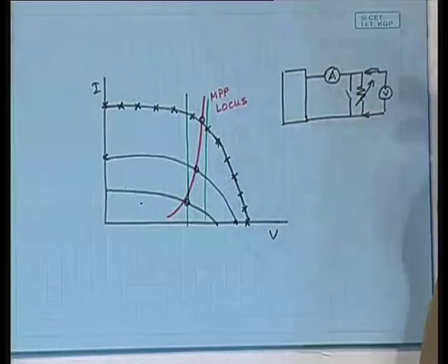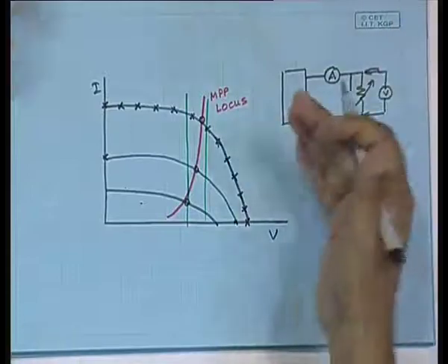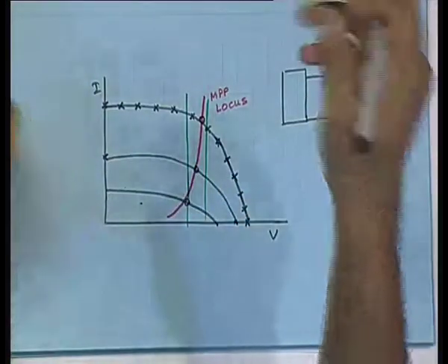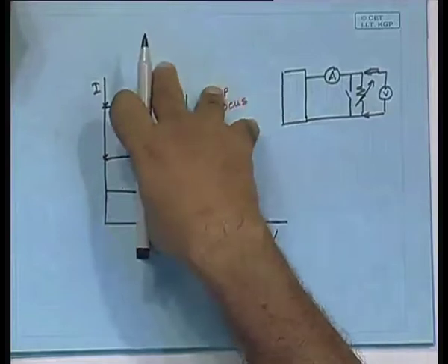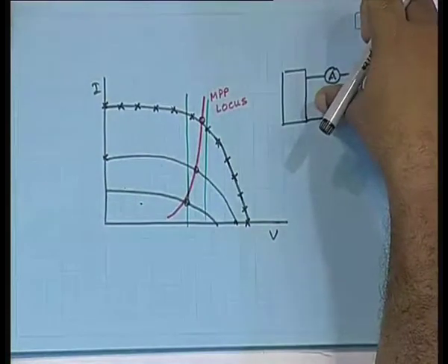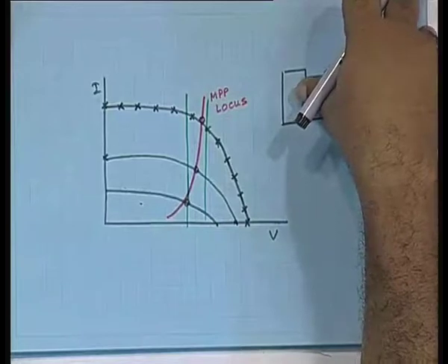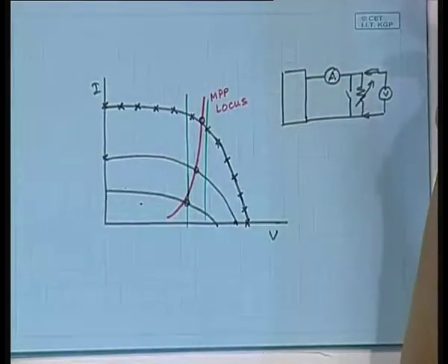So, those who will be energy students, remember this, you have to do it fast and then go to a different inclination, that will mean a different incident solar radiation, do it. All right. Remember, for every photovoltaic panel, this has to be done in order to identify its characteristics and then to find out what kind of load will be suitable for it. Just blindly connecting any kind of load will not help, you will actually be losing most of the energy that you are collecting. Clear?